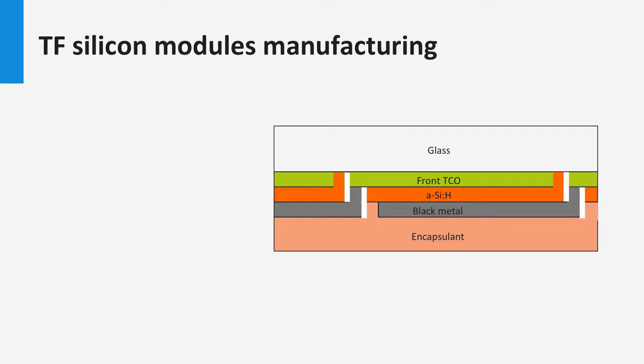The configuration of solar modules of thin film PV technologies is different from those based on crystalline silicon-based wafers. Here we will show the concept of how the solar cells in a thin film PV technology are processed and interconnected. We will show it here for a thin film silicon PV technology. In the next blocks we will discuss other thin film technologies like CIGS and cadmium telluride. Similar interconnection schemes are being used for these technologies.